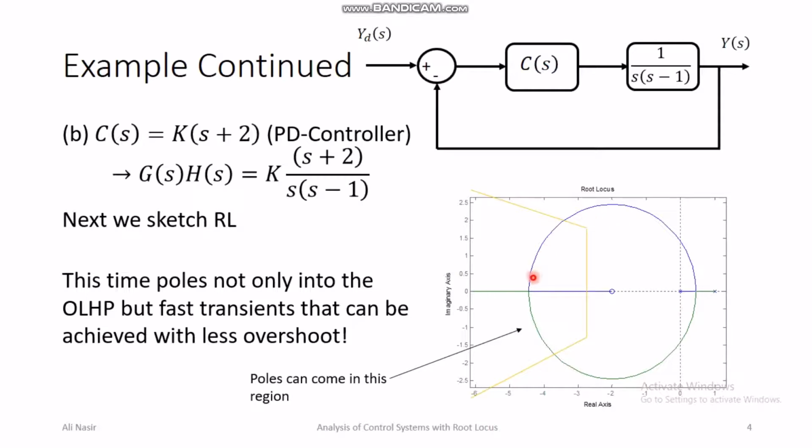But you have to be careful here, because if you increase the gain too much, this pole will go out of this region once again. But then outside the region there is a 0. So once the pole merges into the 0, there is an approximate, not exact but approximate, pole-zero cancellation. And still, to keep both the poles within the left side of this yellow or orange barrier shape, you have to see what the ranges of this gain k are.